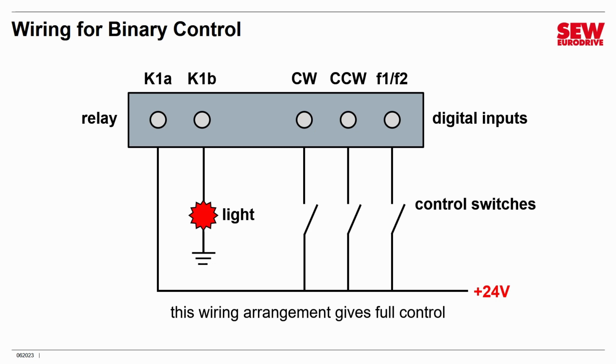So you would do that. If you were using a PLC or something with contacts, you would need to wire it up in a comparable way. Just remember, don't put more than 24 volts onto these inputs.